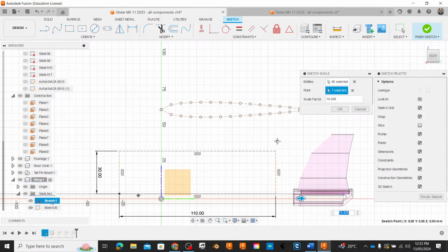I'm going to start about here. I'll use my grid to make sure it's going flat. And I'll cut through my wing profile about here. Oops, I used spline and not line. I'll do that again. So here to here. Finish the line chain with the green tick.